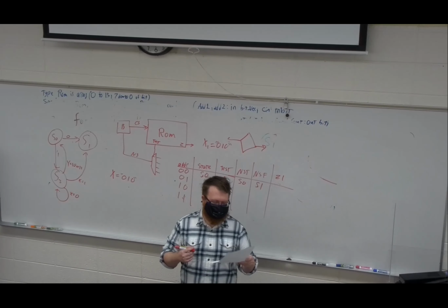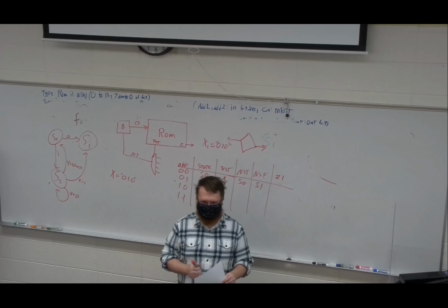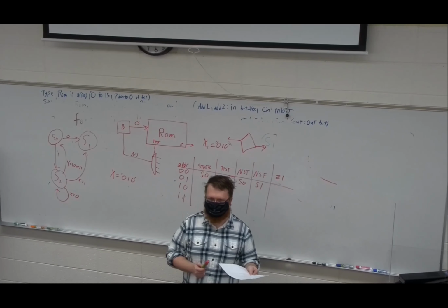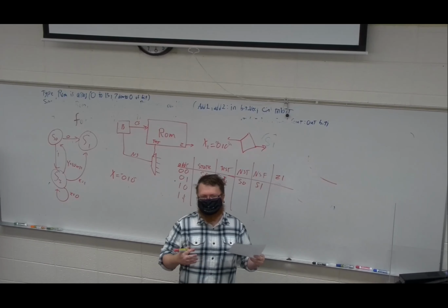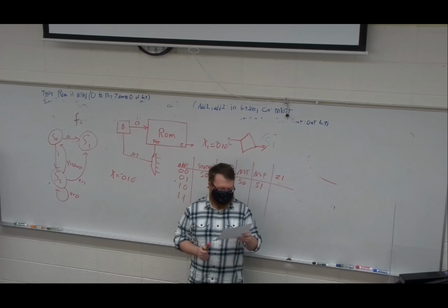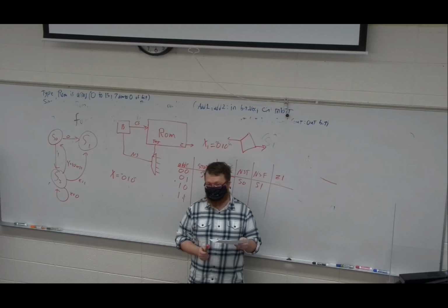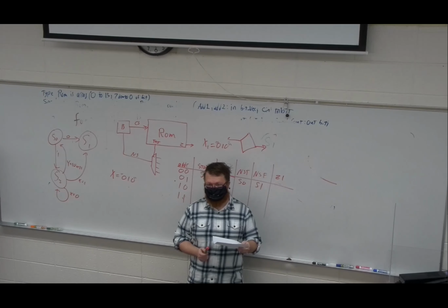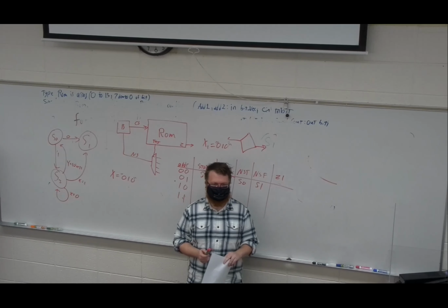I might ask you questions about synthesizable versus non-synthesizable code. I might ask you questions about the SPI protocol and its implementation, right? So we've had that lab. We're supposed to be done with that lab, so all of the questions about SPI are fair game. I might also ask a question like, here is a data sheet for a SPI device. Draw me a state diagram to control this device.